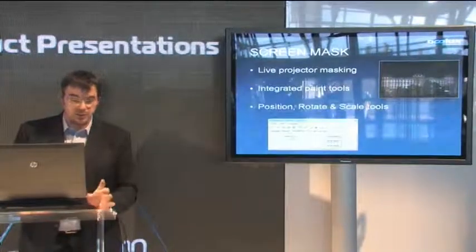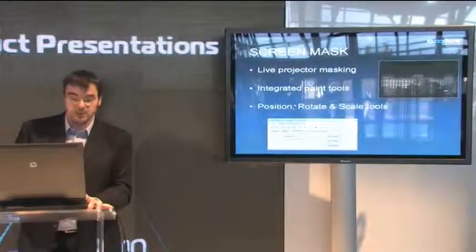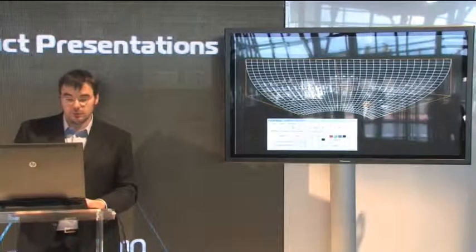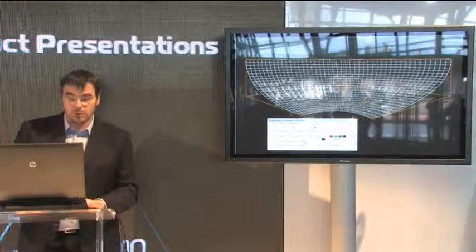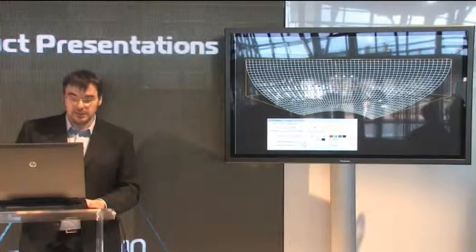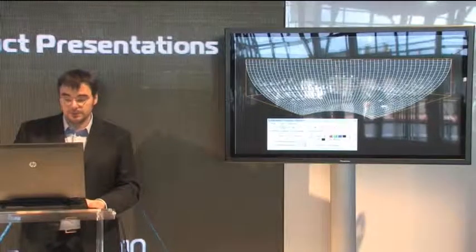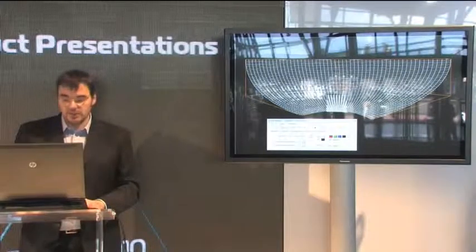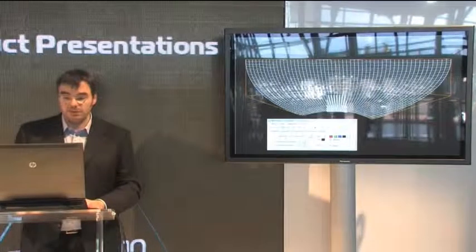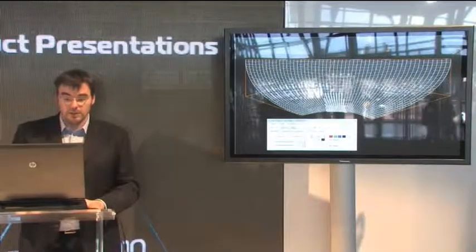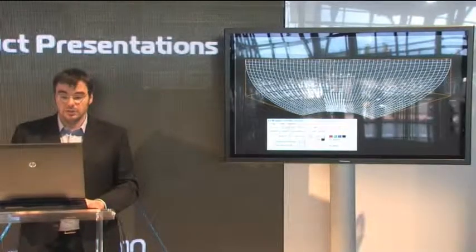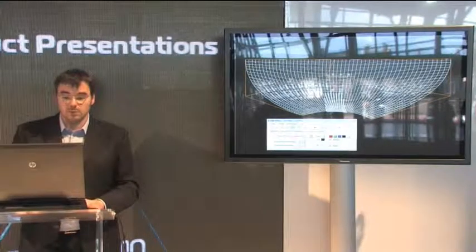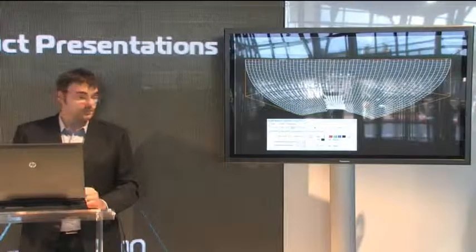Of course, there's some new enhancement on the warping technique, that every individual point can be increased live, so we can change the resolution at any time to have more grid points, up to 99 by 99. And every individual point, we can move individually, offset them from the entire thing, go back to the main FFD, the freeform deformer, or we can rotate that selection. So this is a very easy tool to quickly adjust any kind of warping scenario onto any surface.